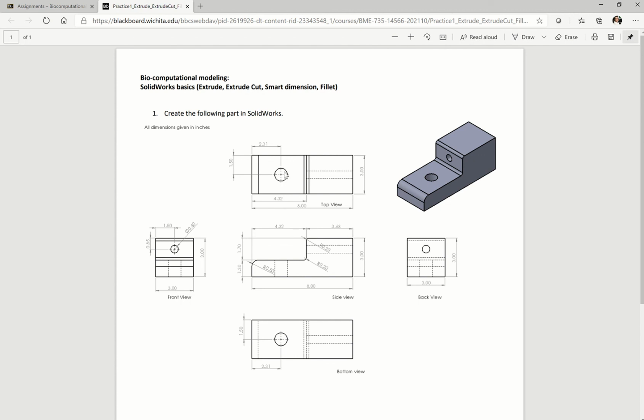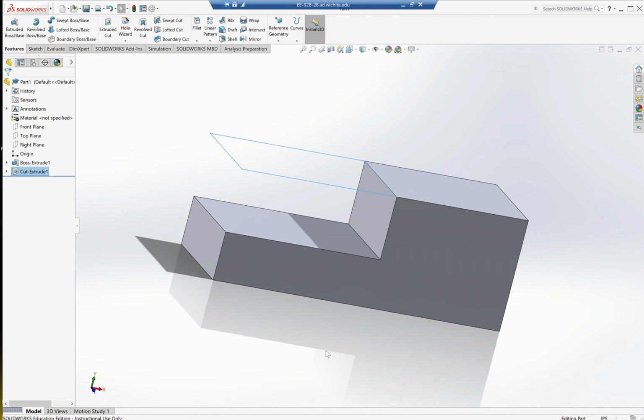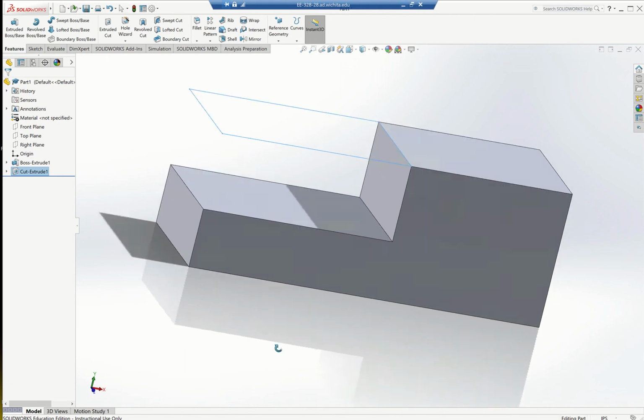Maybe a 1/2 inch or 3/4 of an inch in diameter. Since I didn't put the dimension there, you can make it whatever size looks right to you, okay? But also look that that hole is centered on this top one. It's centered at 2.31 inches in this axis and 1.5 in this other axis. So let me show you how I would put that hole in there.